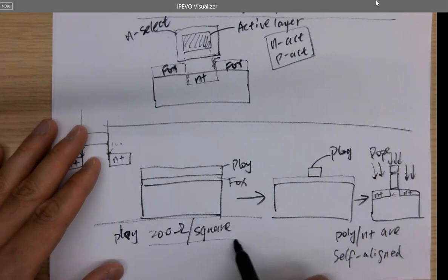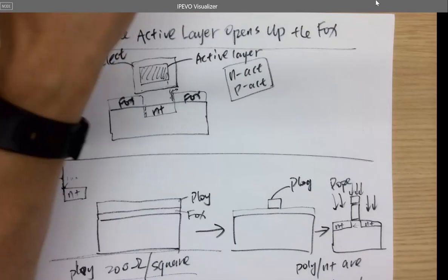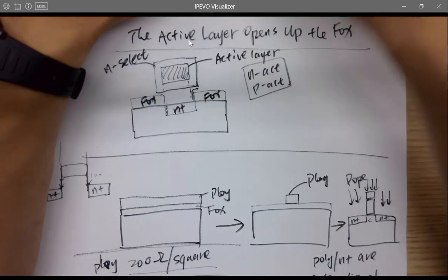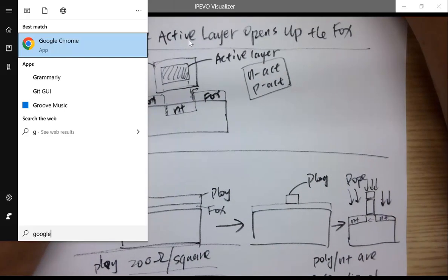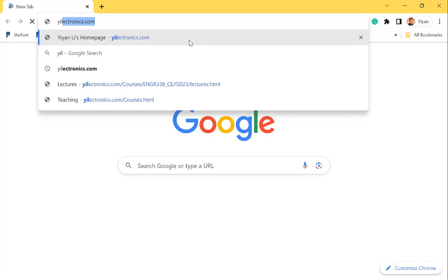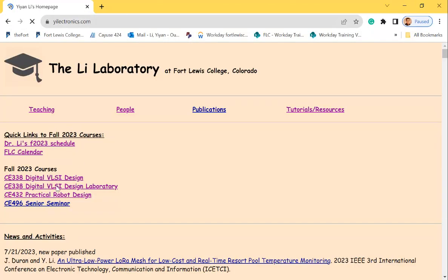It's good to know this because when you are laying out transistors, or use a 3 metal layer technology to lay out a circuit, you will find it's sometimes difficult to route the traces, and you just want to make the poly layer longer, which is bad.